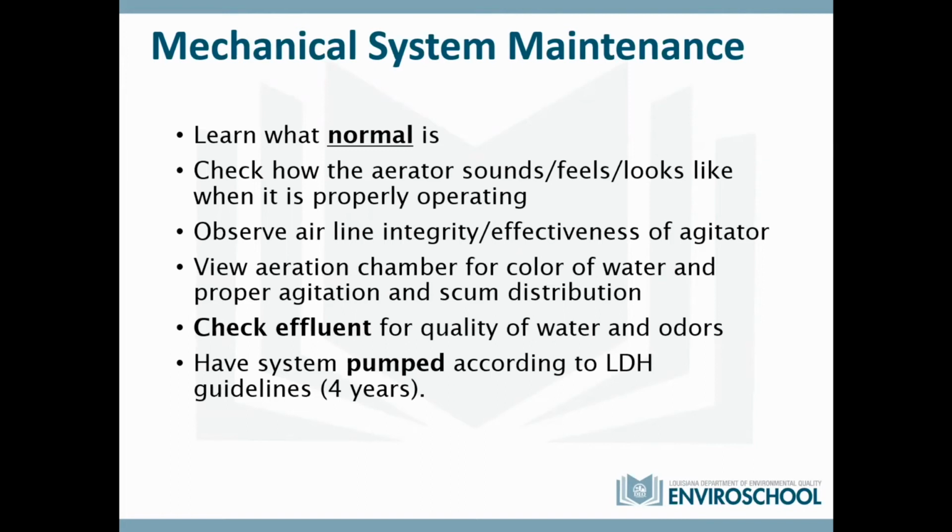So know what your system looks like, what it's supposed to do, how it's supposed to smell. Look at the effluent, see what it looks like when it looks good, and then check it periodically. Because if it changes, if it starts turning brown, if it starts stinking, something needs to be done with your system.